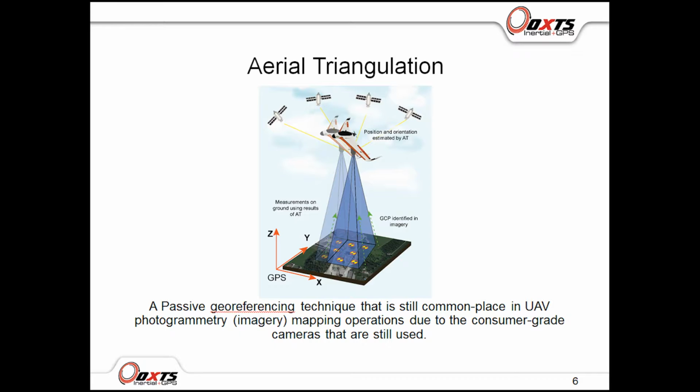By applying this model of external geometry to the data collected by the mapping sensor, it is possible to directly assign known coordinates to the data collected. In the case of aerial imaging, these coordinates might be applied to each frame of an overlapping image set. Or if collecting light detection and ranging data, otherwise known as LiDAR, this model permits individual coordinates to be assigned to each individual data point collected. This process is known as direct georeferencing.